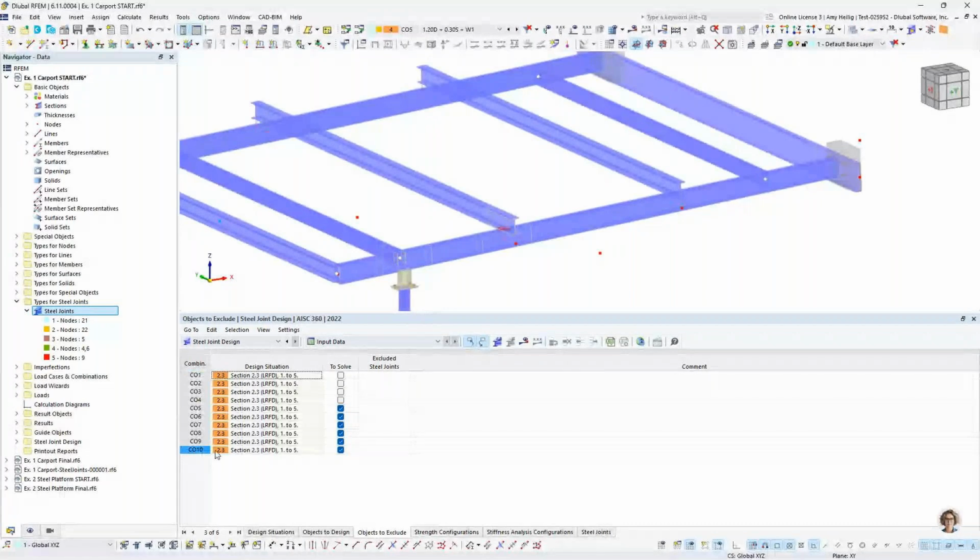And notice that you have the ability to uncheck load combinations. We are generating this submodel underneath the hood, and we are going to rerun each of these submodels through all load combinations. So it's highly recommended that if you know some of these load combinations are not controlling, then certainly uncheck them here so that we're not rerunning them in the submodel, taking up more calculation time.